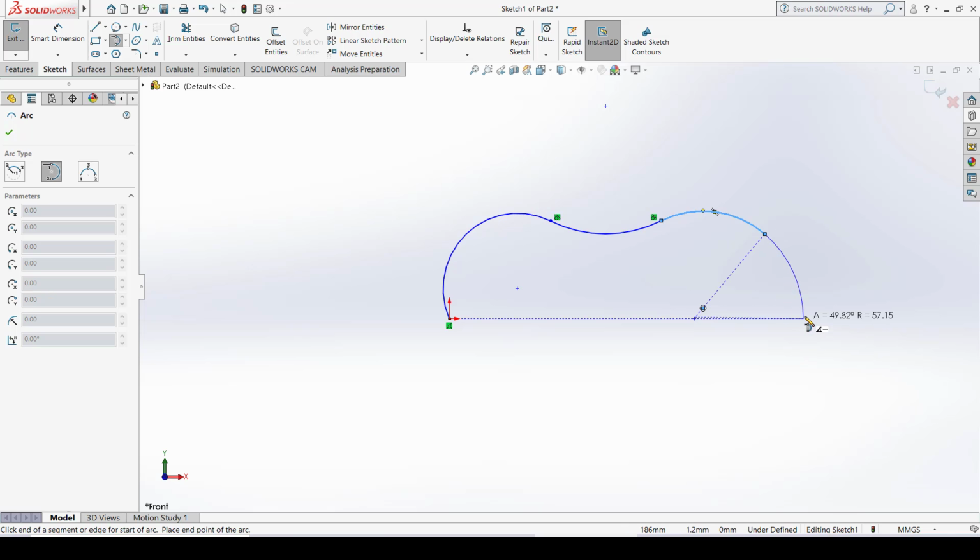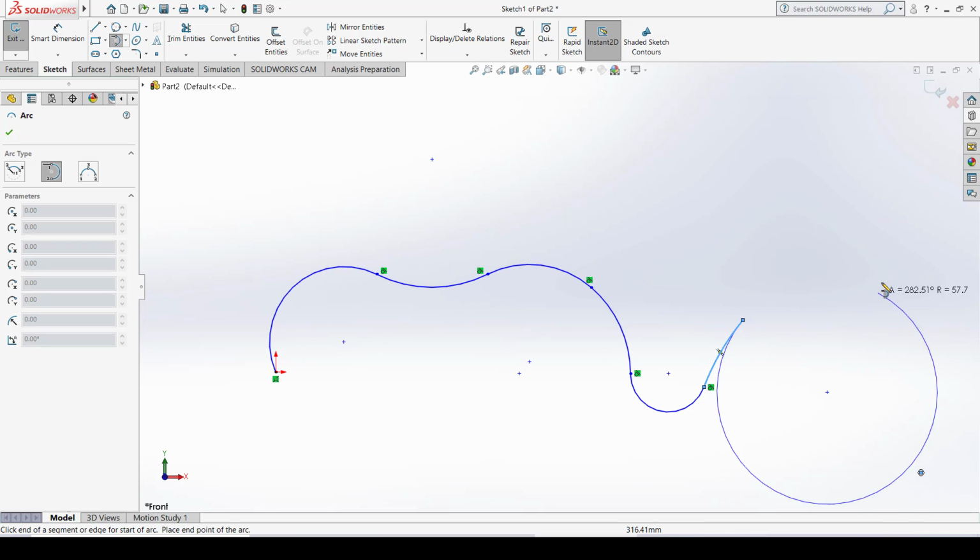Continuous means it doesn't disappear after implementing the command. Just like when you draw a basic standard line, it continues until you cancel the command. Similarly, this tangent arc remains continuous until you cancel the command. Okay, so this is how you can create the arc. This is, we can say, the tangent arc here. Press escape to end the command.